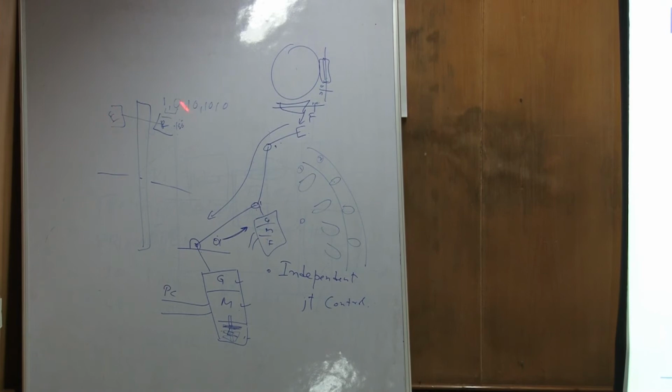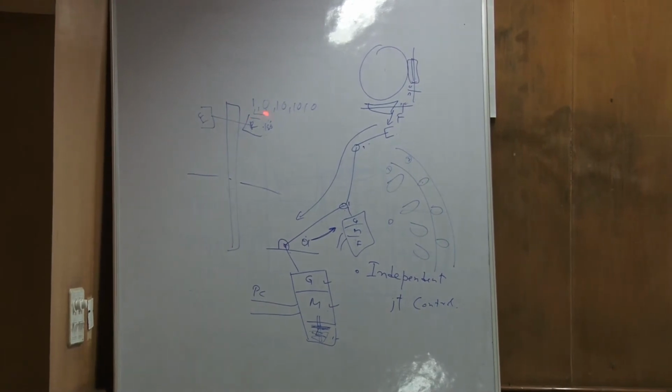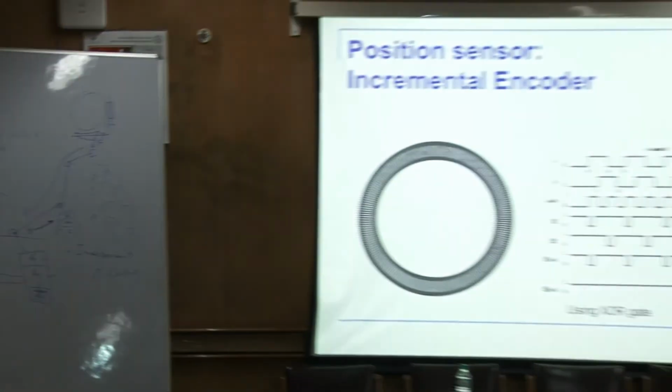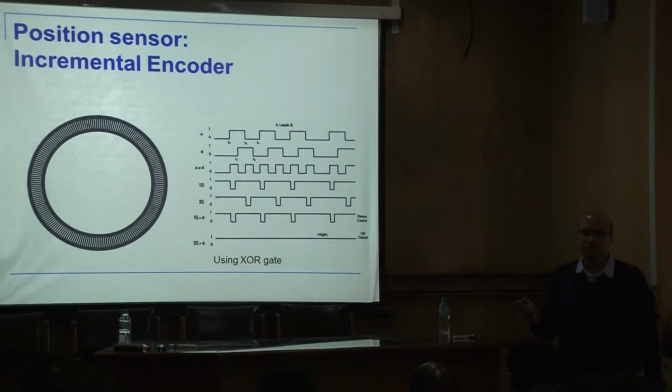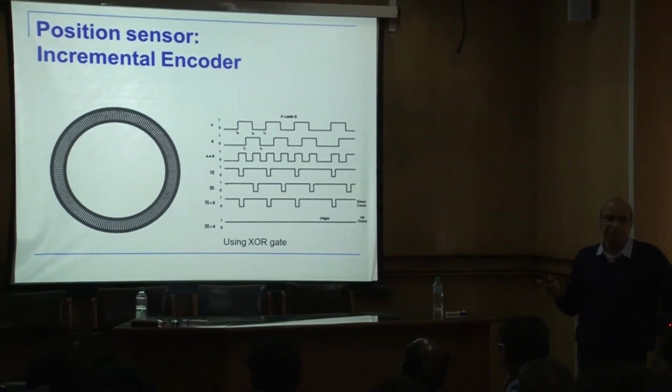Okay. Now how do I get acceleration from that? Where you take the second difference. Okay. So you take the second difference, so you get position, velocity, and acceleration. So this device, which doesn't cost anything, is actually giving you position, velocity, and acceleration. So any controller which uses position, velocity, and acceleration makes use of this only, and can use all kinds of feedback control systems. Very complicated ones with feed forward, velocity feed forward, and also uses this one, because from here you can get velocity and position also. Okay? And that is the reason why 99.9% of position measuring devices are this one.